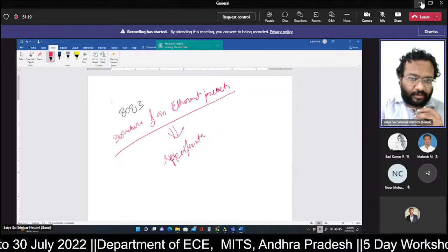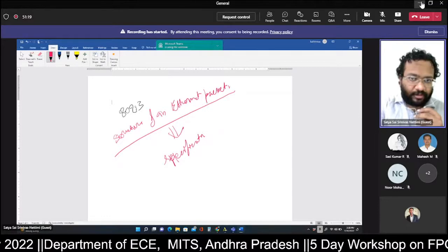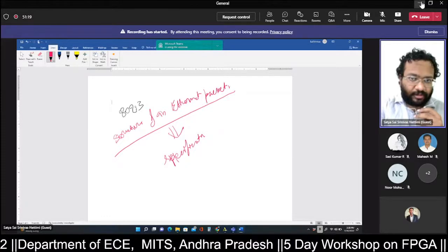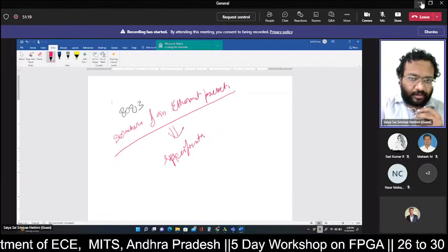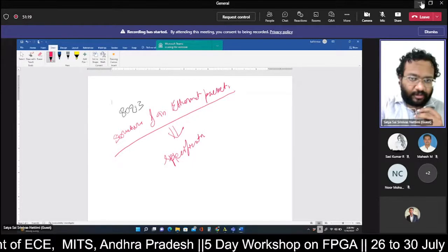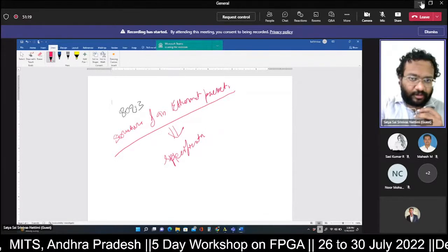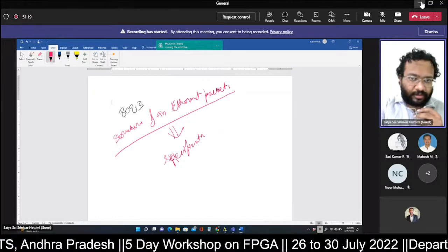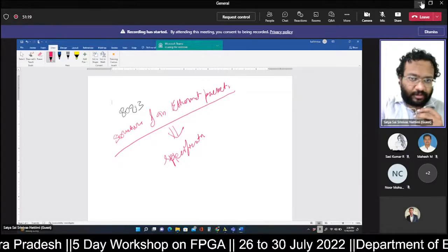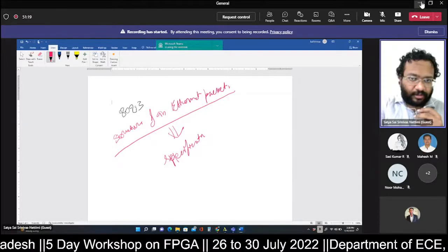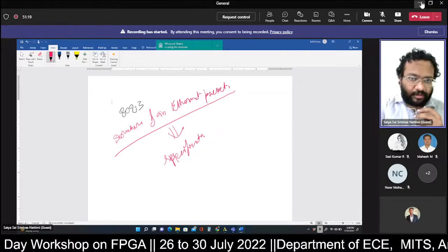Basically, everything is a sequential circuit. Definitely we require an input block. Since it is a generator, we need to give a command input like start, then only it should start generating the frames. Whenever you don't give any command, it should remain in the idle state and it should not generate any Ethernet packet. So for that, we use a control input called start.